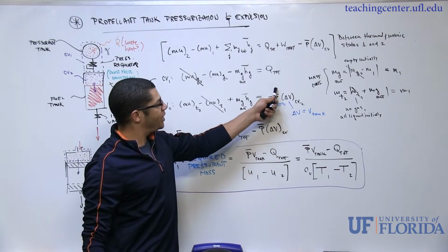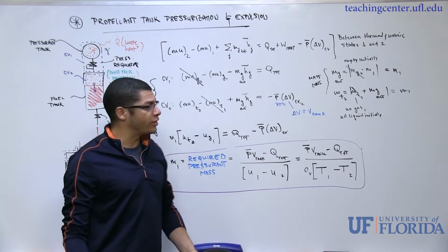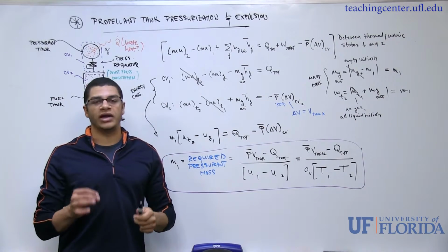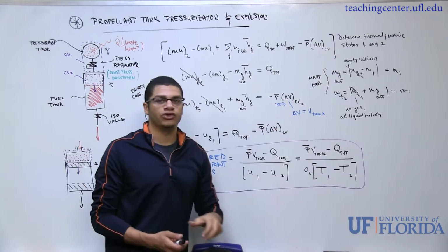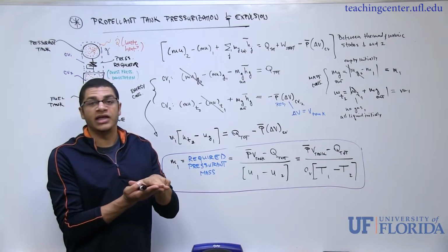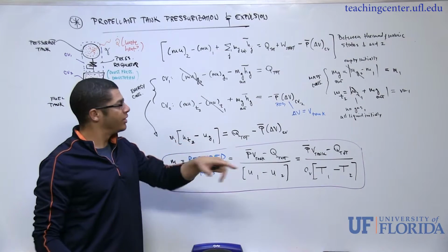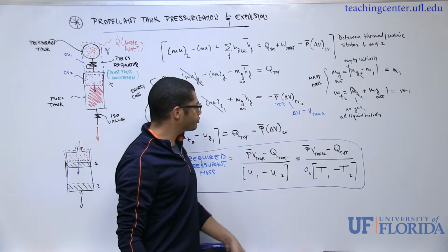So this term, minus P bar delta V, has some significance. This P bar in this particular example would be the pressure that the regulator is set at, and the delta V, because we chose the initial control volume to be infinitesimally small and the final state coincides with the tank, is nothing more than the tank volume itself for the fuel.